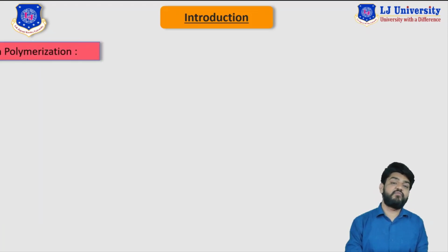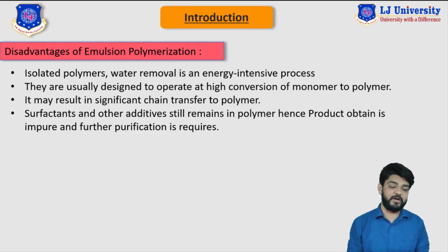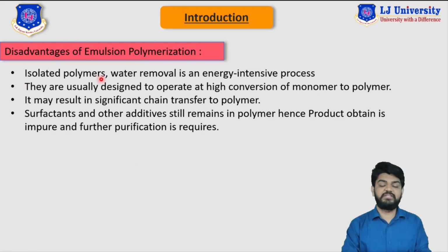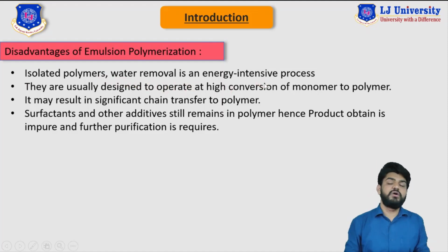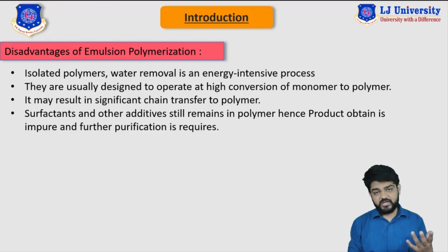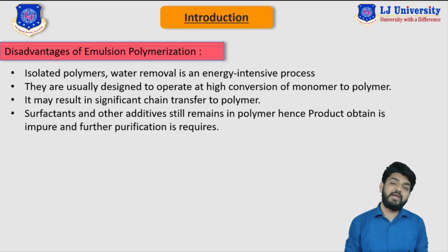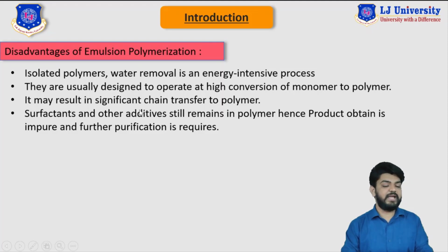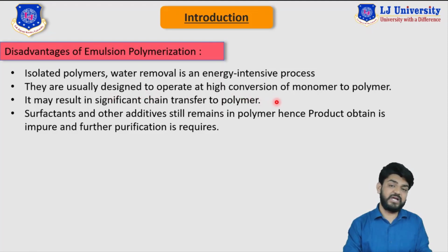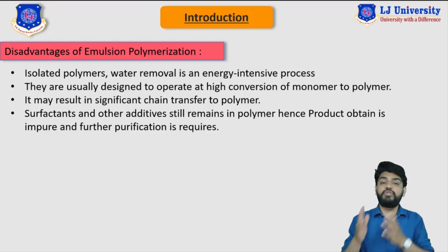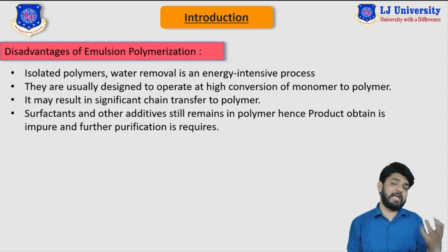Now let's discuss the disadvantages of this particular method. With isolated polymers, water removal is very energy intensive. With this method, we get polymer with water, so to remove the water we require different types of energy intensive techniques. They are usually designed to operate at high conversion of monomer to polymer, which again increases the capital cost and operating cost of the entire system.